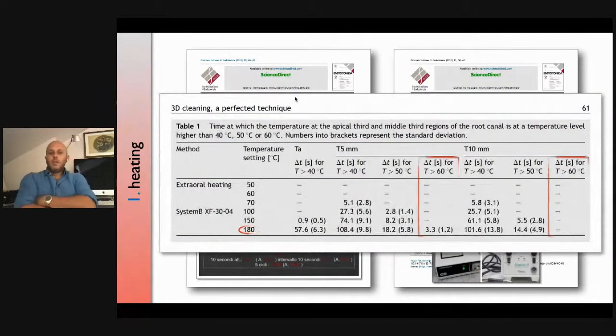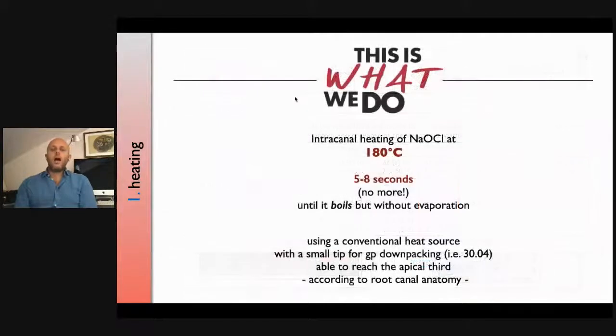And Alfredo, in a research article he published years ago, showed that we can be safe when we heat the sodium hypochlorite at 180 degrees for no more than 8 seconds. So the technique that we introduced is to heat the sodium hypochlorite at 180 Celsius degrees for no more than 8 seconds in order to reach